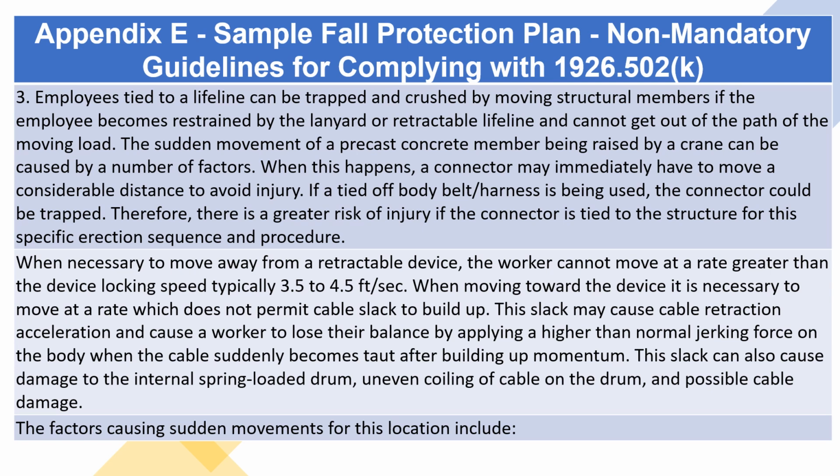3. Employees tied to a lifeline can be trapped and crushed by moving structural members if the employee becomes restrained by the lanyard or retractable lifeline and cannot get out of the path of the moving load. The sudden movement of a precast concrete member being raised by a crane can be caused by a number of factors. When this happens, a connector may immediately have to move a considerable distance to avoid injury. If a tied-off body belt/harness is being used, the connector could be trapped.